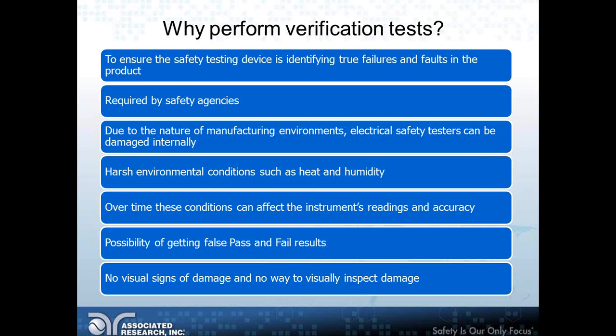So once again, why do we perform verification tests? To ensure that the safety testing device is identifying true failures and faults in the product. It is required by safety agencies, and due to the nature of manufacturing environments, electrical safety testers can get damaged internally.